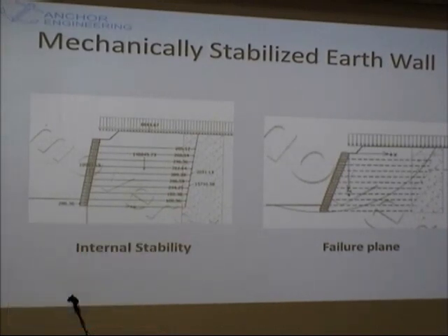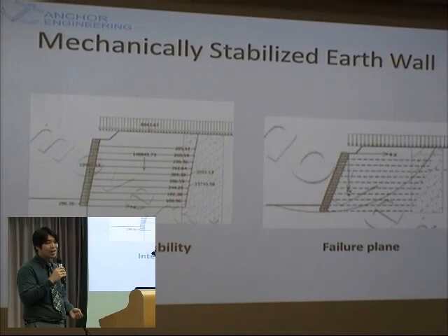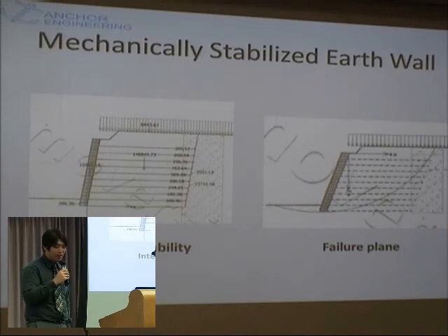The bridge abutment requires 25 feet of clearance to accommodate the rail system. We built it up to 30 feet with 20 blocks offset at 0.2 feet apart. There are 10 geo-reinforcement grids placed 3 feet from each other along the Z-axis. These reinforcement members required a minimum of 7,000 pound-force per foot squared. They also have a reinforcement length of 35 feet.